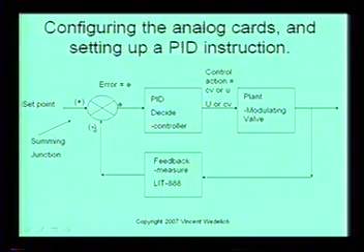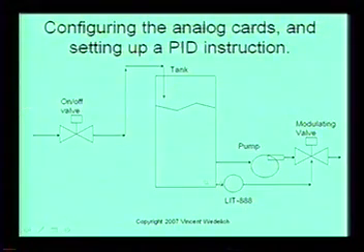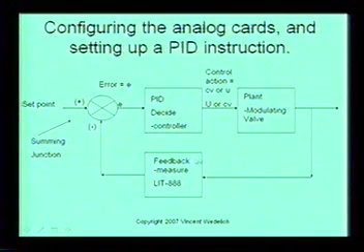This is positive, negative, and this is your error, your PID, your K, your gain, your integral, and your derivative values, and your loop update time, and your min and max value, because you can limit the output here on the action. Okay, so that's actually this tank now put into a PID diagram.